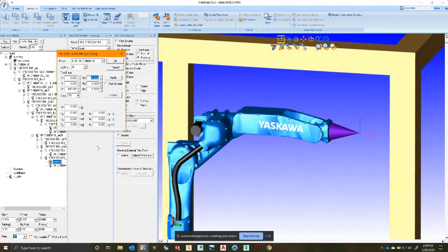If you want accurate cycle time, because most people aren't going to use the full mass of the robot's capability, then you'll want to put the weight in here, plus at the very least one field filled out for center of mass. That's important. That turns off the default parameters, and then it will use these values. In simulation, I've found that the inertia values are not critical. They don't affect cycle time. In real life, they are critical.